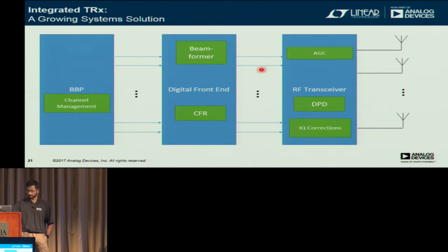So can you just do DPD? Actually, no, because you end up taking on the responsibility for managing the PA. So you say that you want to do closed loop gain control, you want to do VSWR measurements, you want to do PA bias control, a whole bunch of other things that you're signing up for.